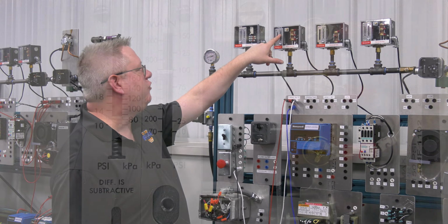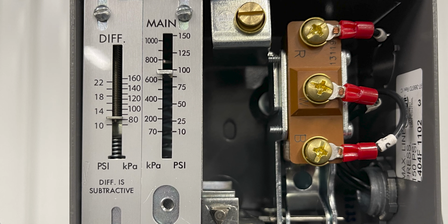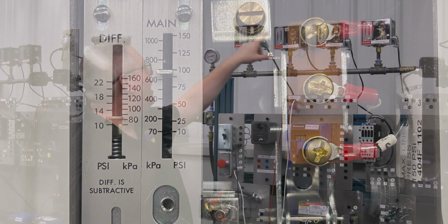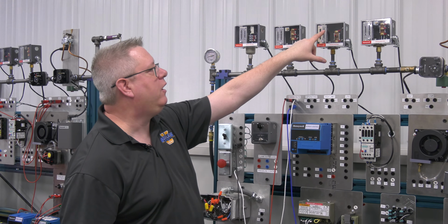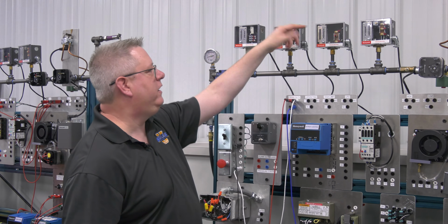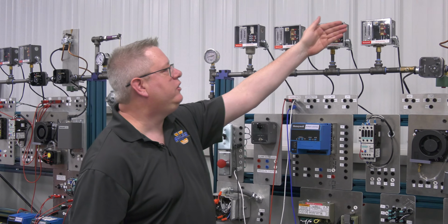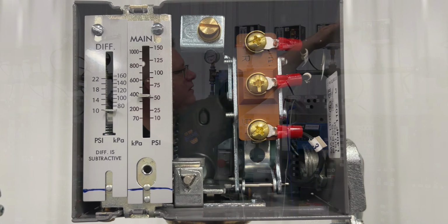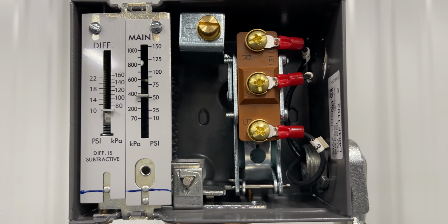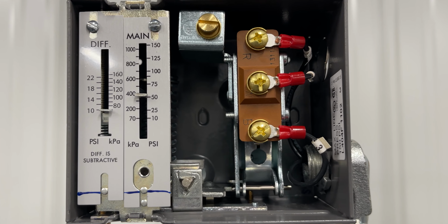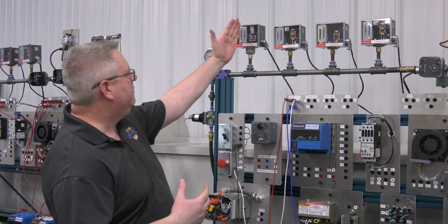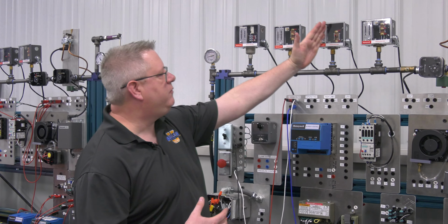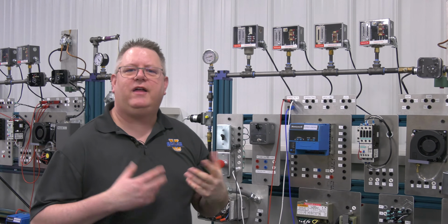Your operating control, if you look at the dial on it, is typically going to be set above your firing rate control and below your, I'm sorry, your manual reset high limit. Your low fire hold is going to be set lower because it's designed to operate at a far lower pressure to enable the boiler to go to the modulation state. So firing rate, operator, high limit, low fire hold, that's great.